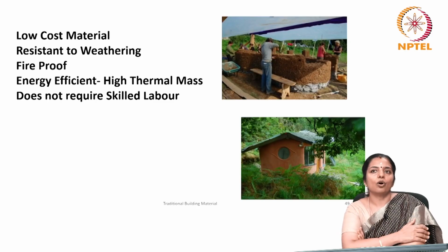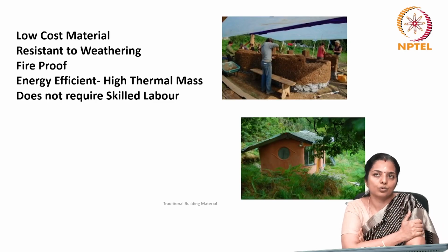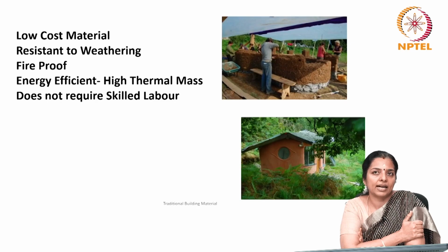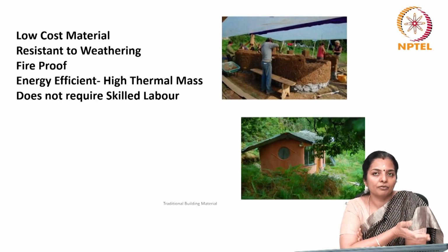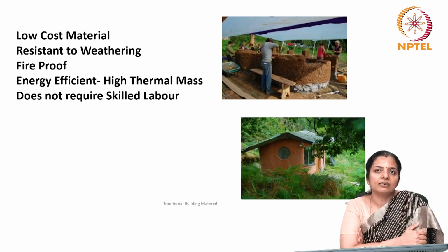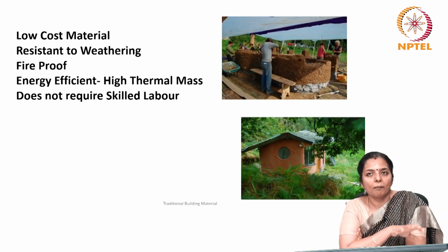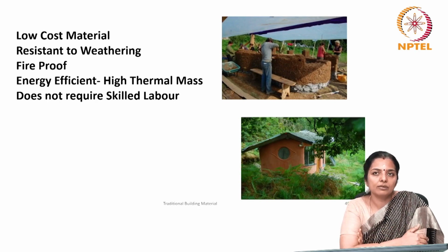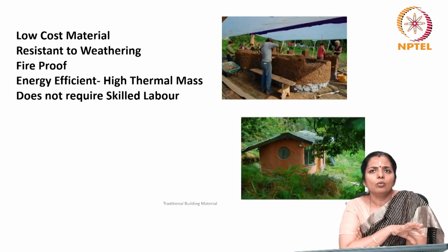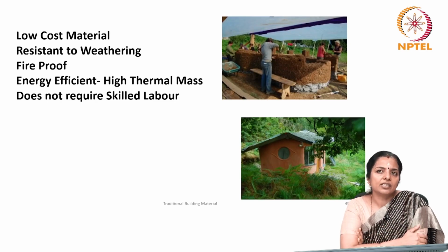Now, the basics of cob building method, as we saw, was to have a mix of clay, sand, straw and water, using our hands or feet rather, mixing the needed into a small lump, which is then compacted and shaped by hand to create walls and foundation. Now, the subsoil naturally varies in composition, but it can be altered with sand or clay depending on what is more or what is less, if it does not have the correct combination.